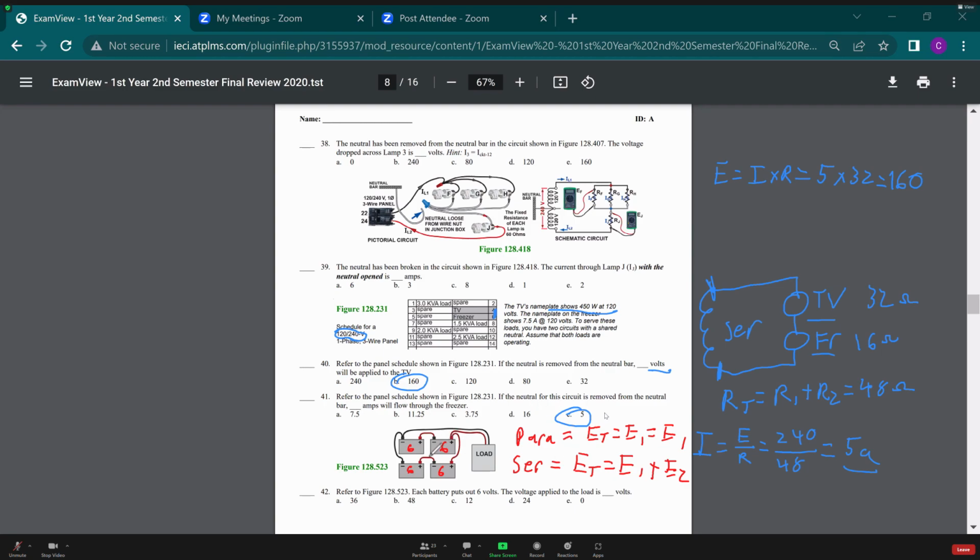So looking at this top set here, I have a positive to negative connection. So I know that these two batteries are in series, just like this bottom set, positive to negative. This bottom set is in series. But if I take a look at my top set and bottom set, I can see I have positive to positive and I have negative to negative.